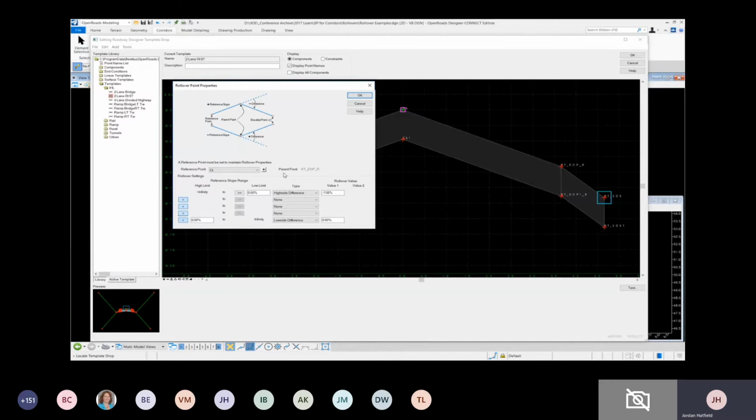In this case, looking from a positive slope on high side super, we would have from infinity coming down to 0% on the high side difference, which is just managing the handed curve here, more or less the positive and negative value. We have a -7 algebraic difference. On the low side, from 0% down to negative infinity, we have planar lock. Basically, the shoulder is the same slope as the road once it's greater than the 4% of the shoulder. So once this lane becomes 4%, they lock and they move on. That's the difference between why we have the high side and low side differences.